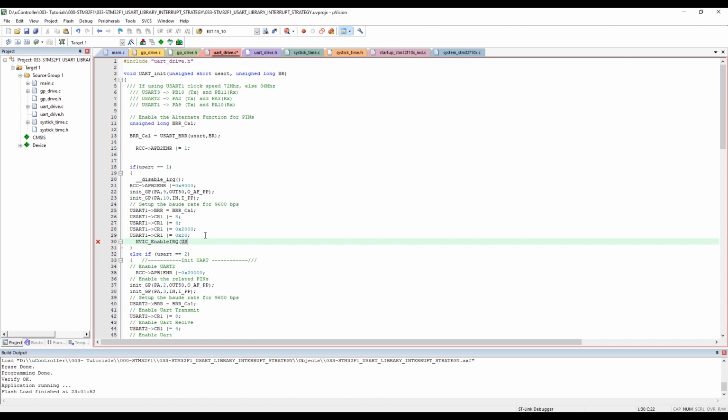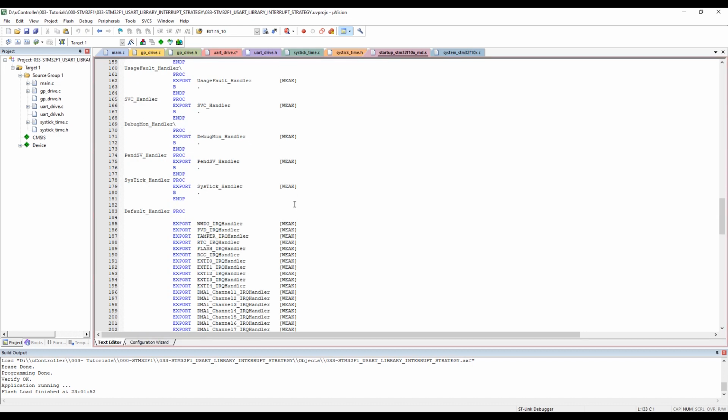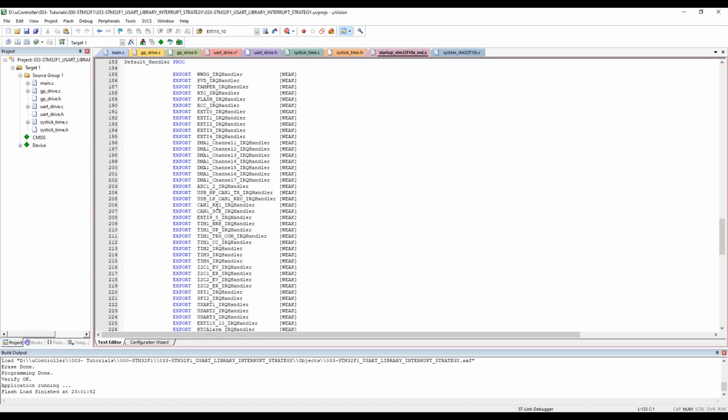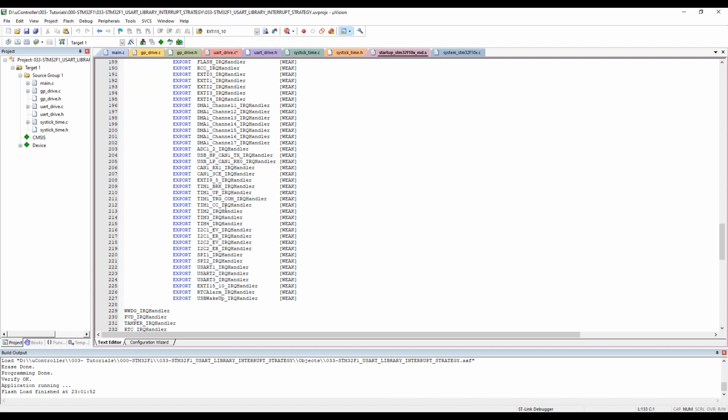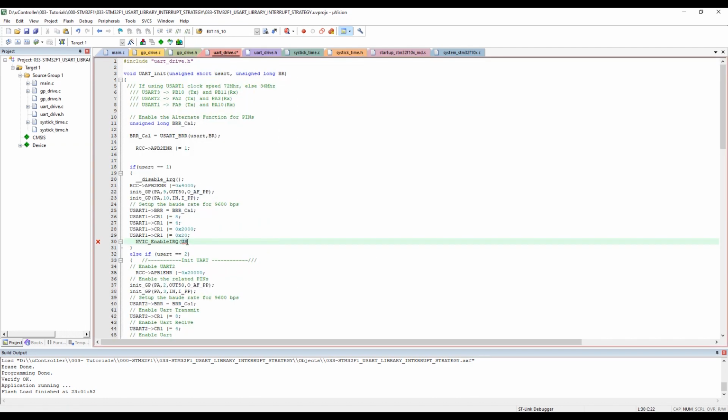If you have any doubt, each time you run your system, this window is open, and here you can see all the interrupt routines, so you can see the name like this. You just copy UART1 and go back here to make it easier. IRQ, oh no, sorry, not handler, but IRQn.